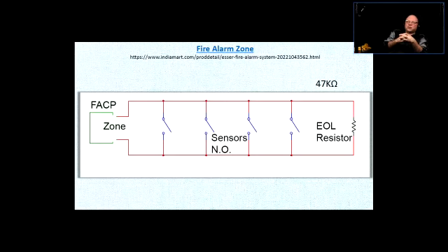And the sensors or the zones can be organized. For example, one of the triggering points, which would be the zone that's connected to the main panel, could have 2 wires going in a bus type of configuration, and it could extend along the whole length of a certain hallway, right? In that hallway, there could be a bunch of smoke detectors pinned up to that zone, and that zone could be called East Wing Hallway Smoke, right?